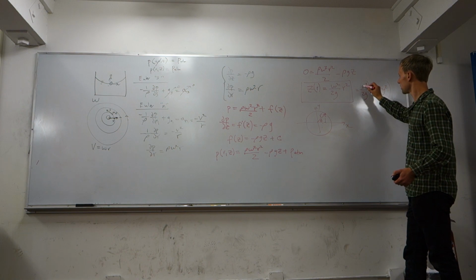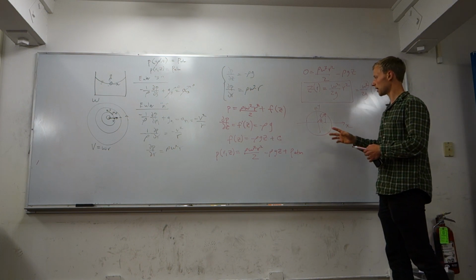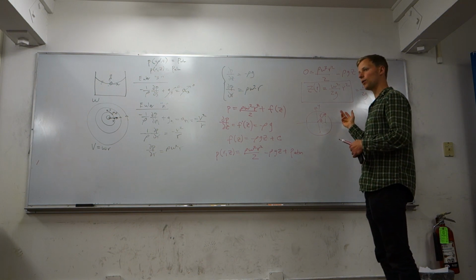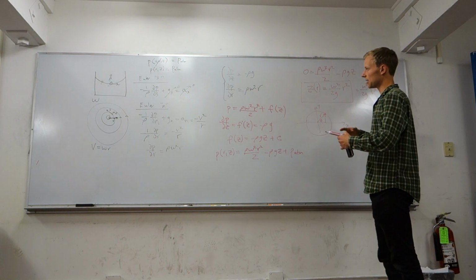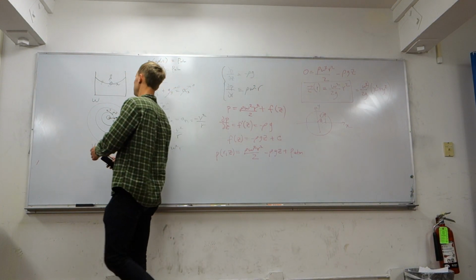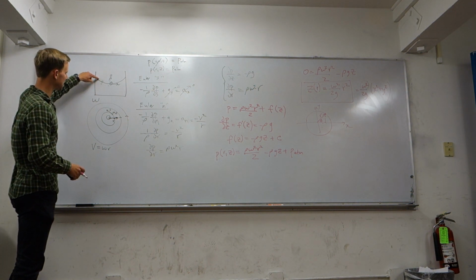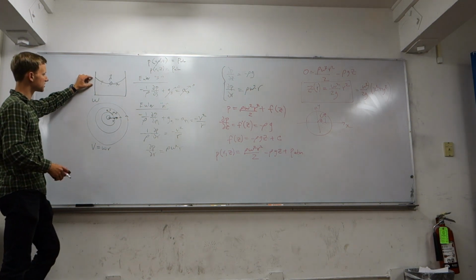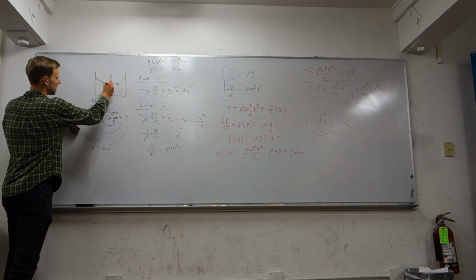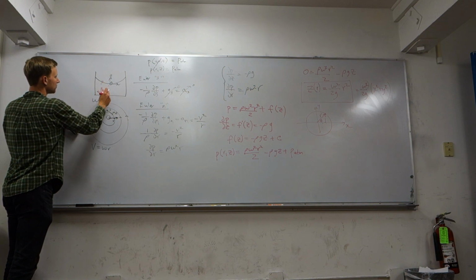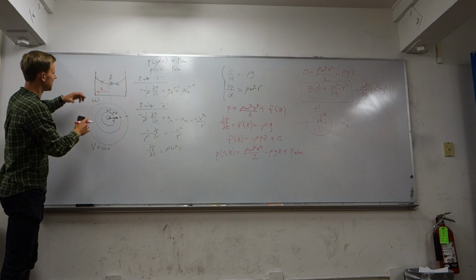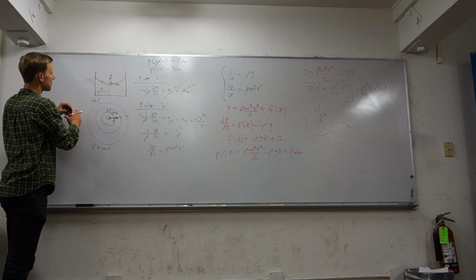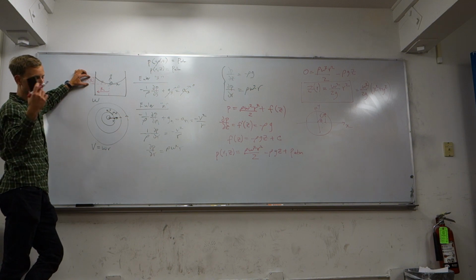So what we're going to do is try to confirm our analytical expression for the free surface with an experiment. Ideally we'd be able to find the shape at every point along this flow. But a simple way of checking to make sure it's a parabola is to find the height of the function at our distance capital R from the center, and see if this height, z as a function of capital R, matches our experiment and our model.